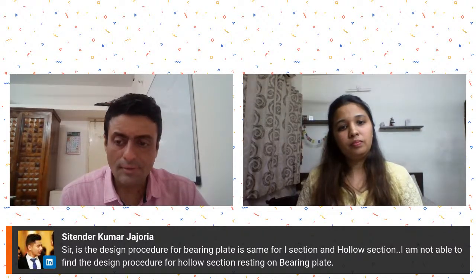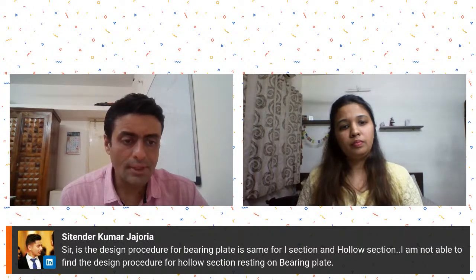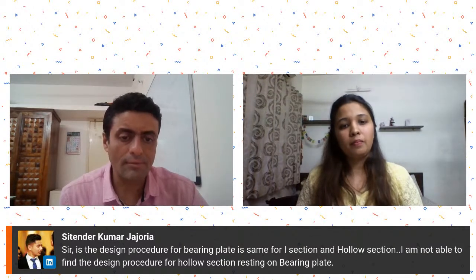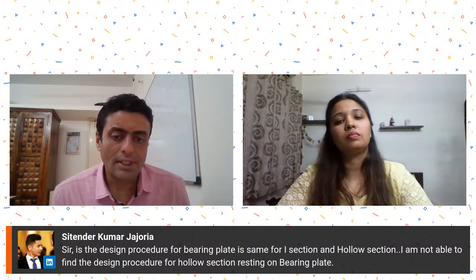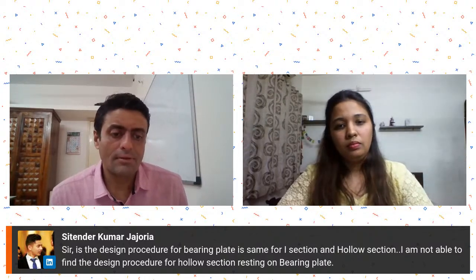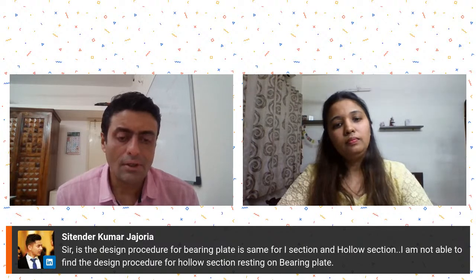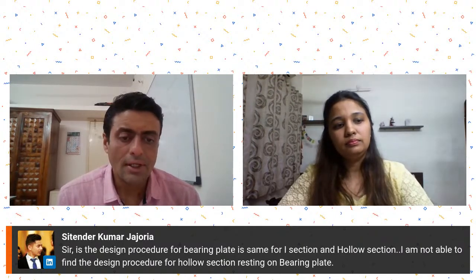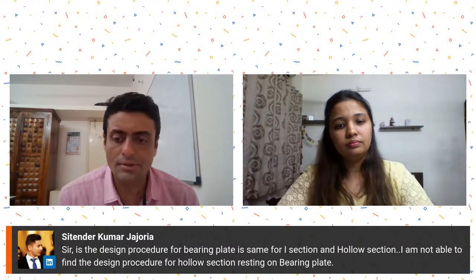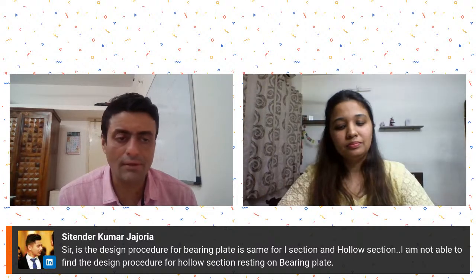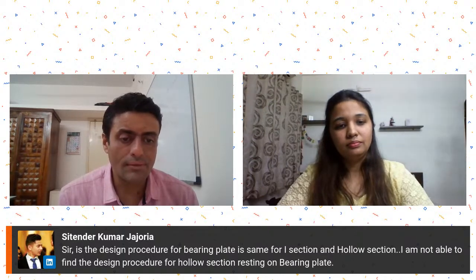In the design procedure for bearing plate, is it the same for I section and hollow section? I am not able to find the design procedure for hollow sections resting on bearing plate. I think the overall procedure will remain the same, just that you will have two web plates to take the bearing stresses or the reactions. In an I section we only have one web plate to check the strength; here we will have two.